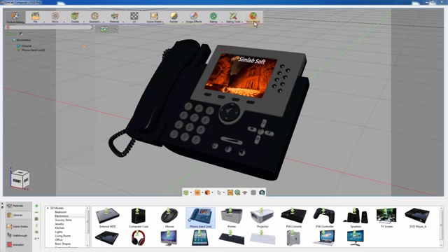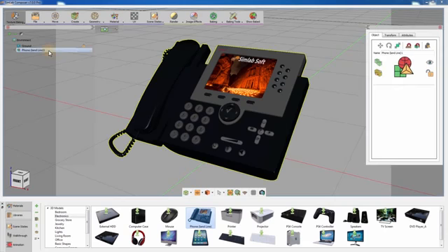Select the objects you intend to bake, or the main group in the objects tree if you intend to bake all the geometries in the scene, and from the Baking Tools menu, select Info. The number of objects in this scene is 52, which means that texture baking will produce 52 texture maps for this model, which could be a little excessive.